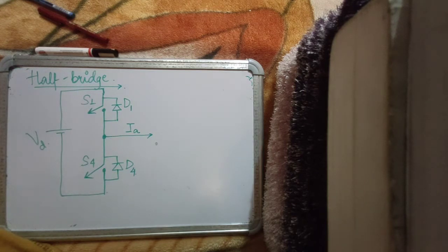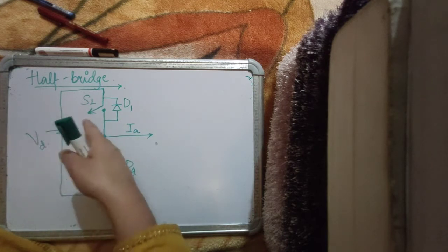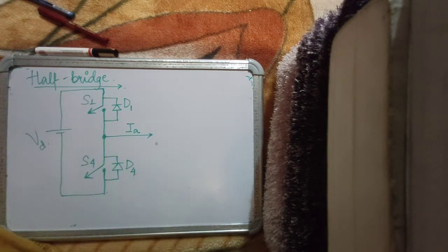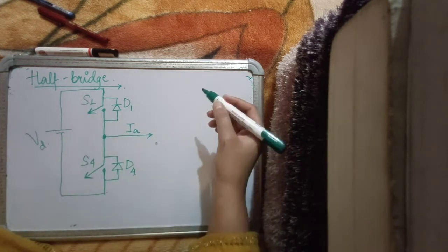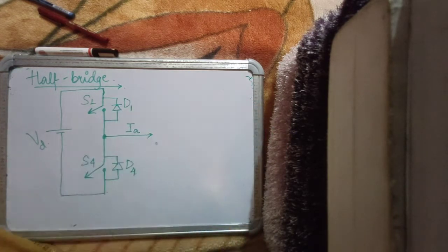Now in a small switching interval, whether you are switching from S1 to S4 or you're switching from S4 to S1, in every small switching interval, we assume that IA is constant, because basically IA is a low frequency signal, say a 50 Hertz signal, but the switching frequencies correspond to say 10,000 Hertz or 20 kilohertz or 30 kilohertz or even more.